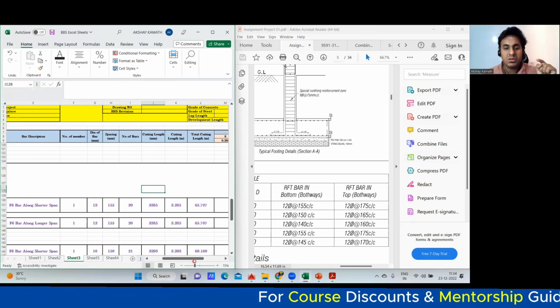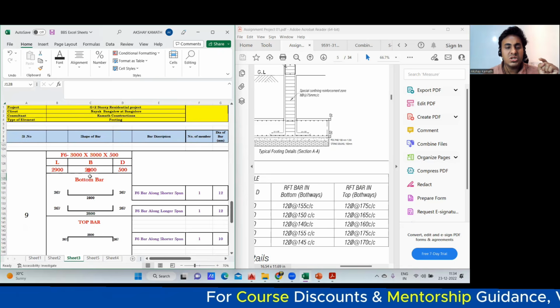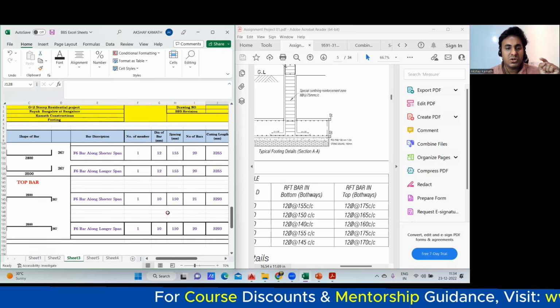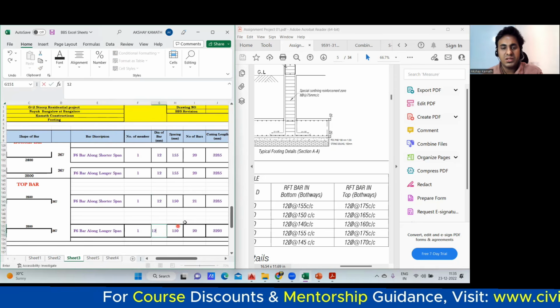This is top reinforcement. Similarly, come here. Top also you change. So once you change here, automatically this part also will change. Only the thing is you have to change this part now. Okay. This is 12 diameter. No, make it 12. This is also 12. Why? You know the reason.